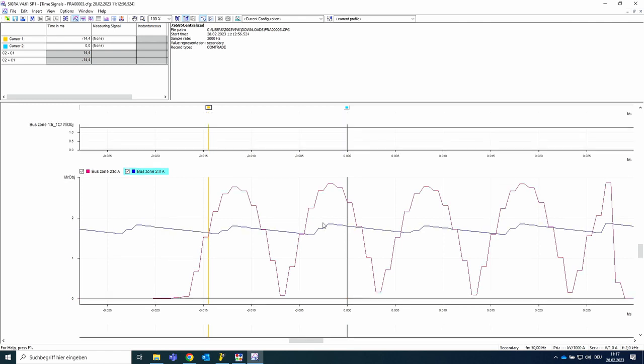And here we have the first possibility, and here a little bit on the right side, to be a little bit more realistic. And now we will start the 2 out of 2 algorithm. If you remember, with the 2 out of 2 algorithm, 1 threshold exceeding is enough. But to be sure to start the second measurement window in the second half wave, we are starting a rest and break of the measurement of 8 milliseconds.